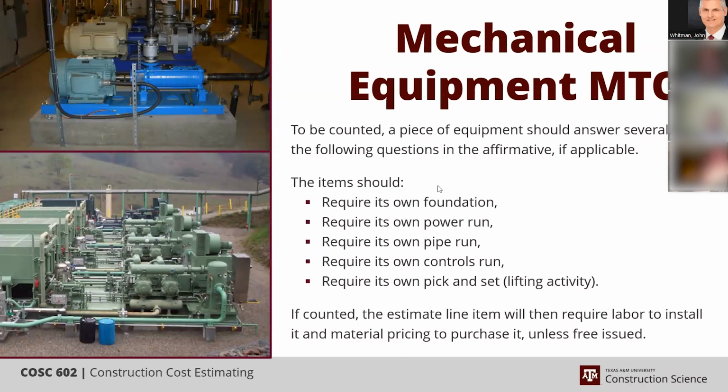So a company that has been tracking their histories well will know that for low density polyethylene, or for chemical plants in general, we have these metrics. For every piece of equipment, we have so many cubic yards of concrete, lineal feet of pipe, lineal feet of cabling, so many instruments, and so many tons of steel related to each piece of equipment.